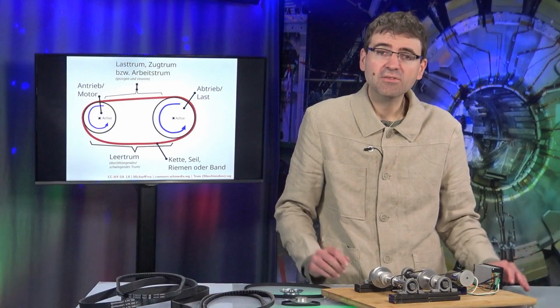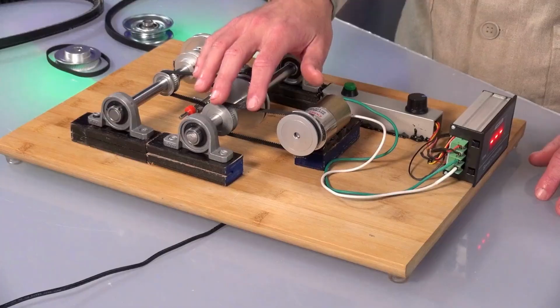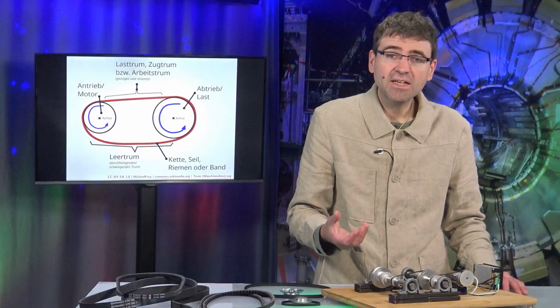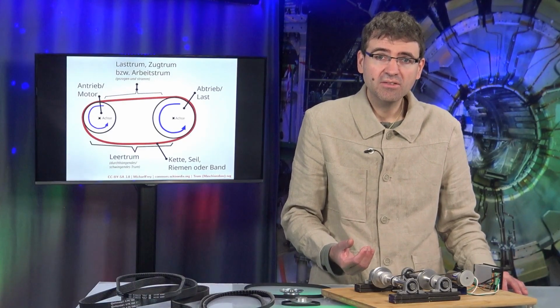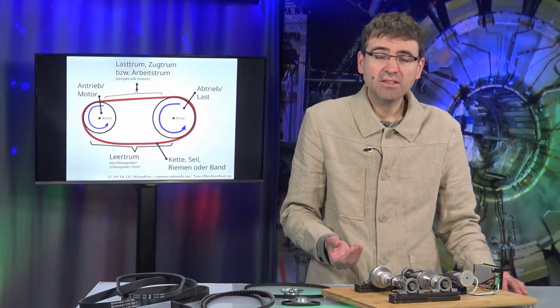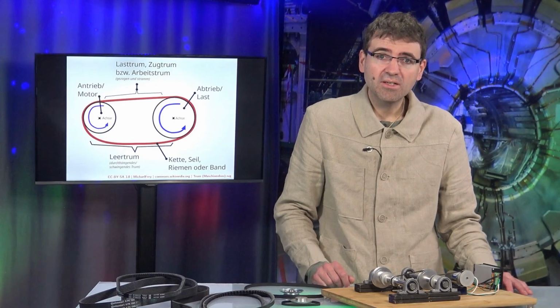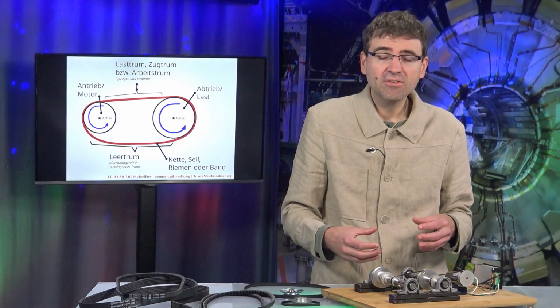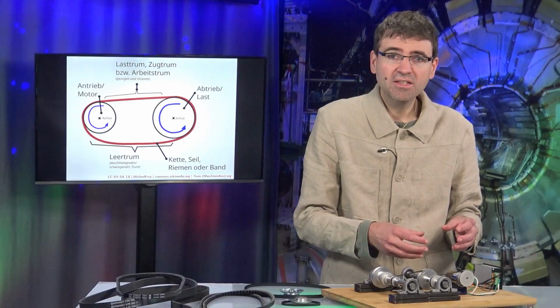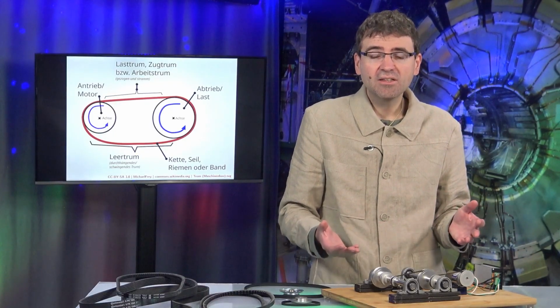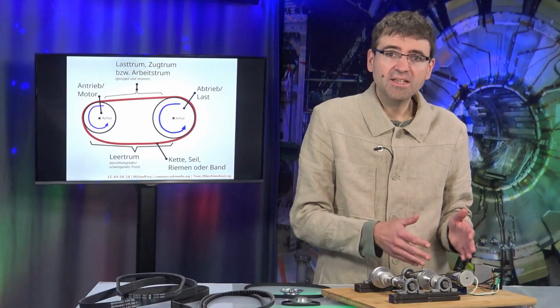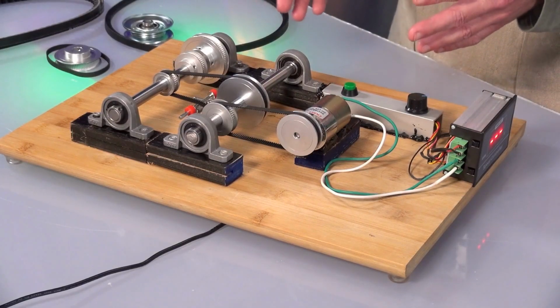On a guitar, for example, we can tune the string, and the string vibrates at its inherent frequency. We are able to measure this natural frequency. And this natural frequency also correlates with the length of the belt and its mass per unit of length, per kilogram. If we know the units, we can determine the belt's tensile force via the frequency, and thereby have the opportunity to verify if we are within an acceptable tolerance range or if adjustments are necessary.